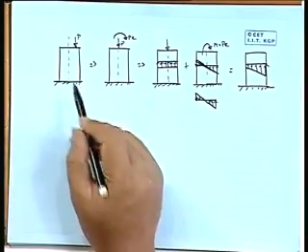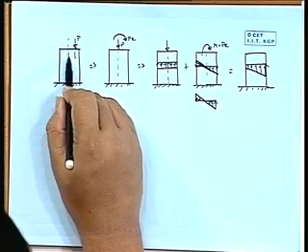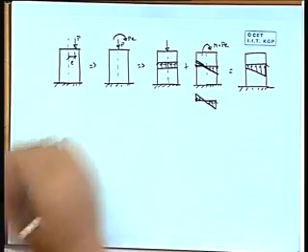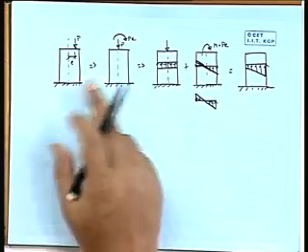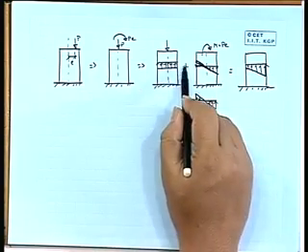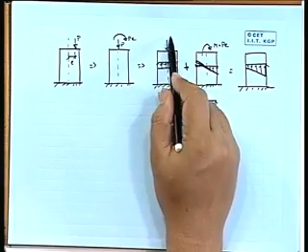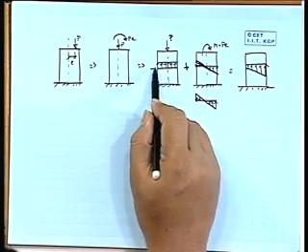so the actual load is P here. That distance we have defined as E. The load we have shifted to the centroid comes with the moment P into E. So that part we can just add in a separate way. So there is a load P here that will give the stress distribution. That part we have already defined.